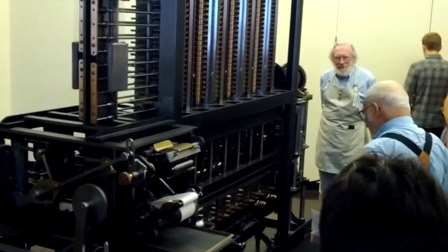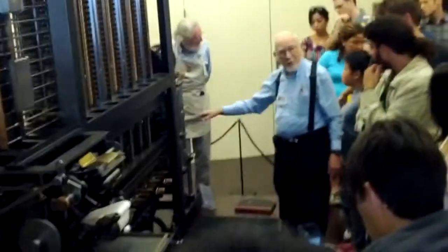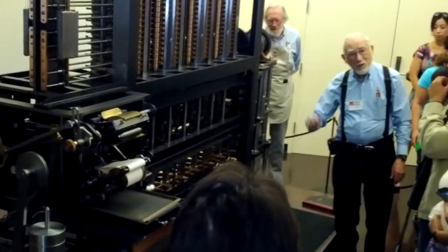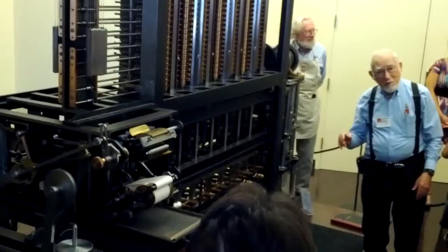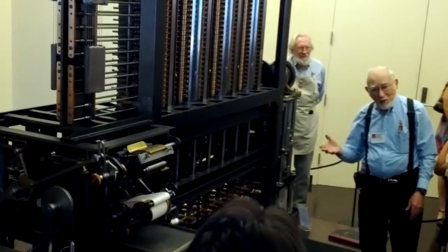Oh, one other thing. The program, the thing which works everything, are these cams. Every one of these cams makes something move at the right time, which causes either a vertical motion or rotary motion. There are 2 cams for every motion. One pulls, one pushes. We don't have springs as cam followers.